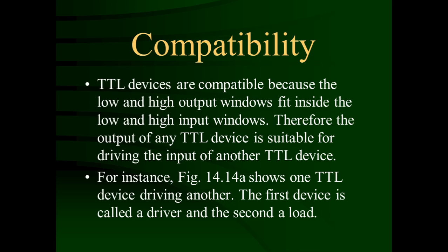Similarly, the output window from 2.4 volt to 5 volt fits inside the input window of 2 volt to 5 volt when it is in the high state. So, the output windows fit inside the TTL input windows, and hence we can say that they have compatibility.